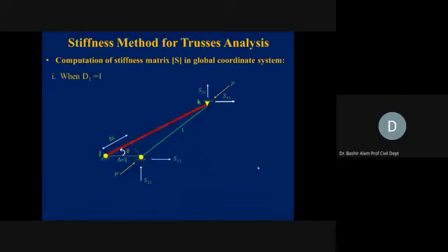So here, along the D1 direction, if you see, this was originally joint J and we displaced it to delta equal to 1. So it is coming to this right roller location. And this green one, you see, this is becoming the length of this member. And obviously you can see this green length is less than this red one, which was the original.